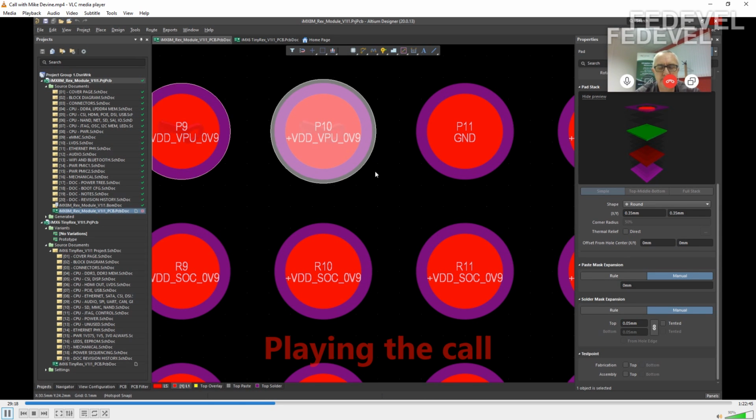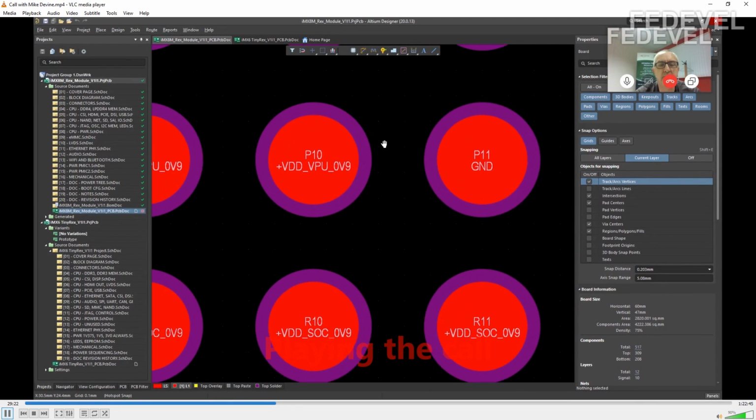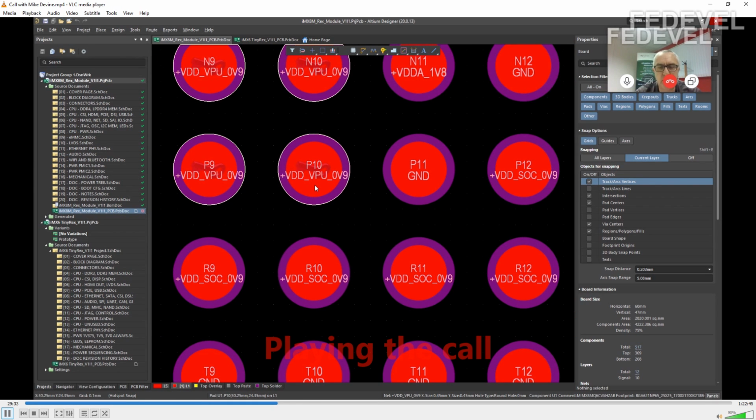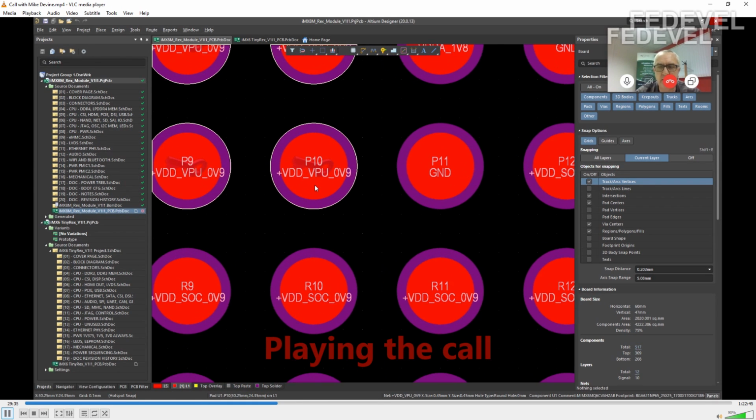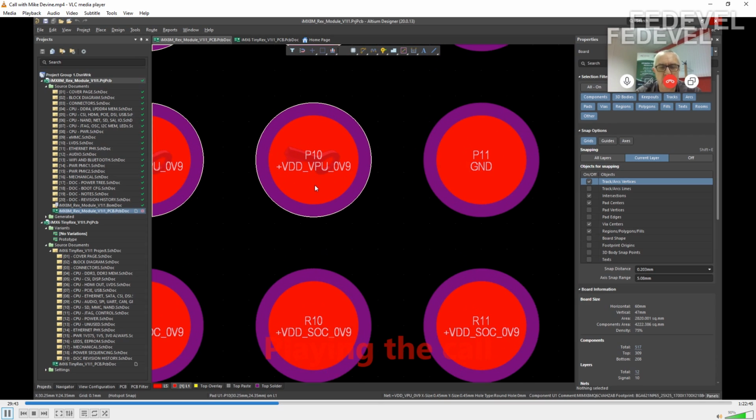Okay, so for this kind of design, if I would like to place these through hole filled vias into power pads, I should use the copper filled PCB. Yeah, correct, Robert. Yes, I would go for that version. I think you'll get a much more robust product. Yes, it may take 2-3 days longer to manufacture, but the end product would be far more robust.